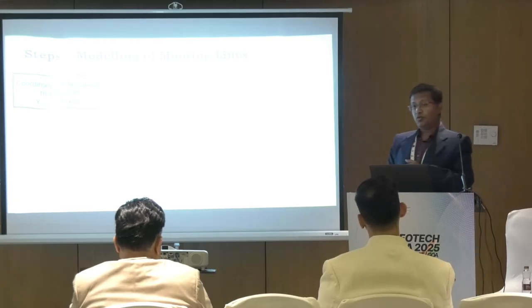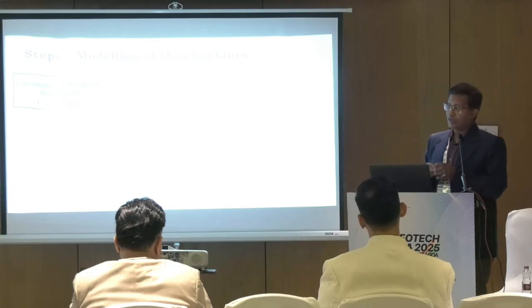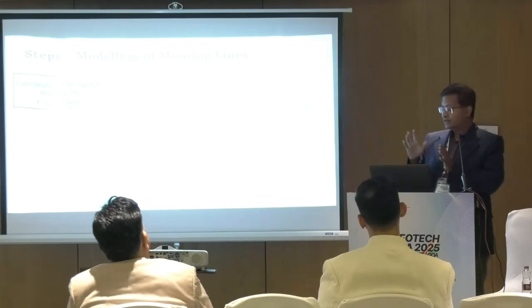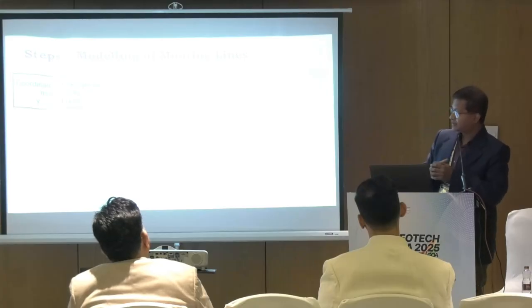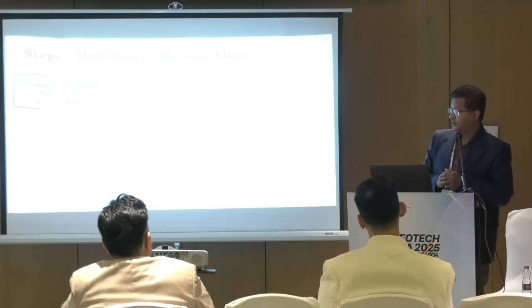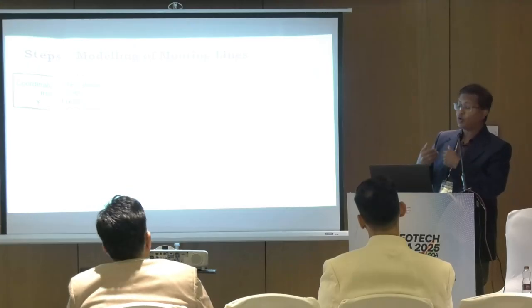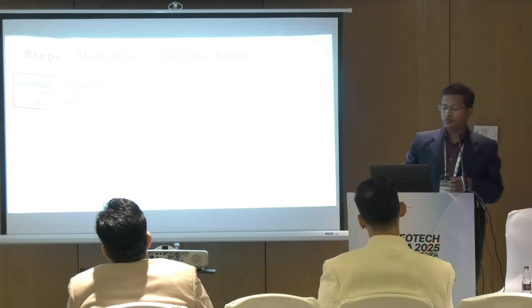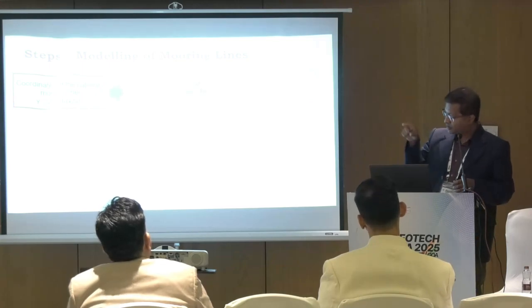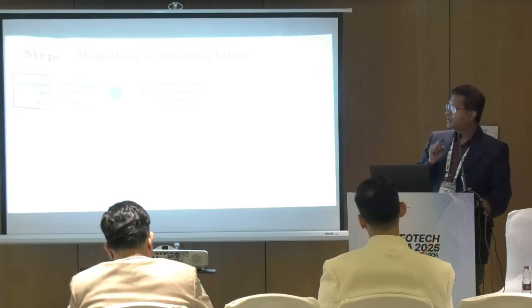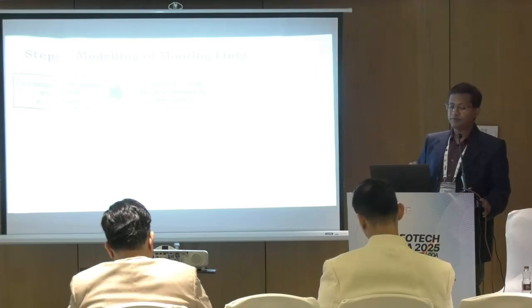The modeling of the mooring line is also challenging. At present, beam elements are available. Those who are doing numerical modeling will understand this. The mooring lines are a very flexible system, so there is a lot of challenge in modeling this kind of structure. So what we have used: first, you have to find the coordinates of the catenary mooring line using this equation.